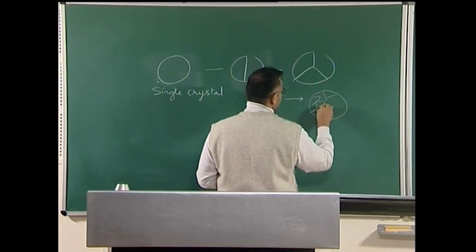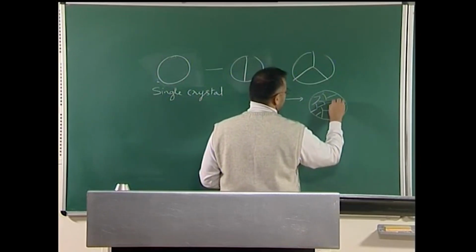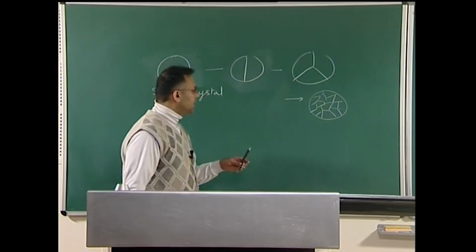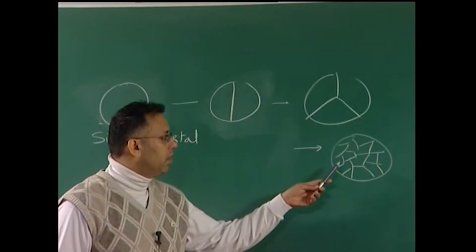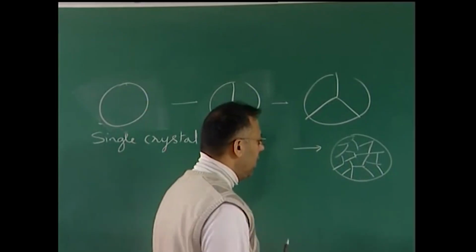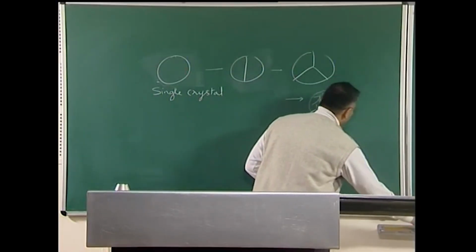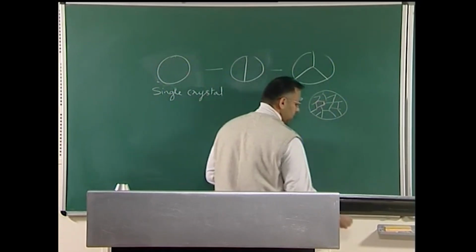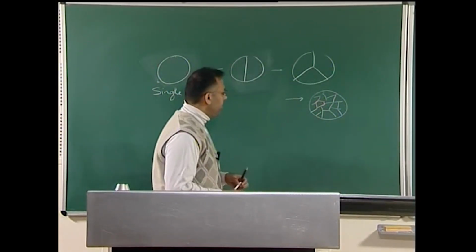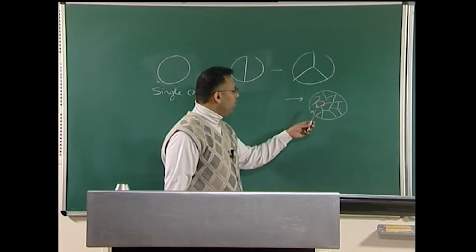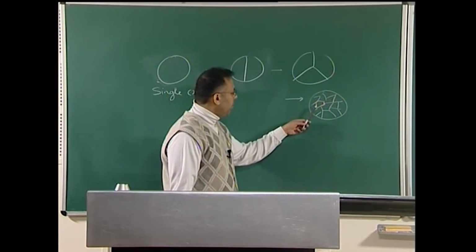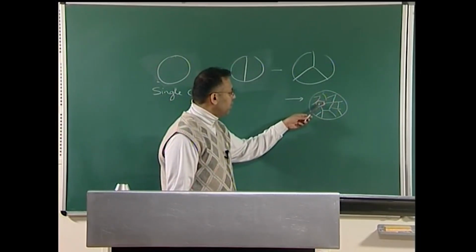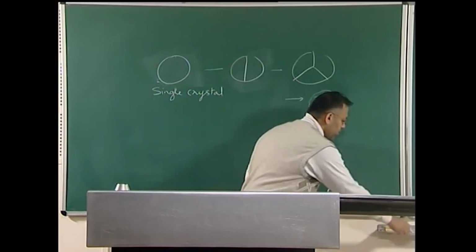In this case, this is a schematic division. In this case, the particle size is not reducing, it is actually the grain size which is reducing, and this implies that my grain boundary area or my interface area is going to drastically increase. Now, this has profound consequences, like if we are talking about grain boundary diffusion, or creep dominated by grain boundary diffusion, then these kinds of effects will start to dominate when I reduce my grain size to these values.